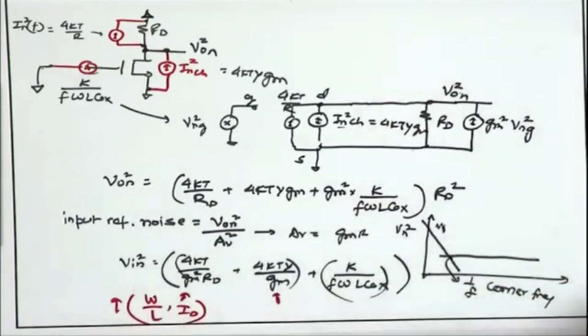So, we will start our discussion on the front end amplifier, start with the building blocks, the differential amplifier with active load. We will also look into current mirrors, and then finally develop the entire scheme with appropriate DC biasing, with optimization of noise, with optimization of bandwidth, and looking at the complete picture. And then we will use that front end amplifier with some other signal processing schemes to take care of some of the critical issues like this 1 upon f noise, especially in case we are dealing with very low frequency signals. So, that is going to be covered tomorrow, and hopefully we will be completing the analysis of a front end amplifier based on the material that we have prepared today.